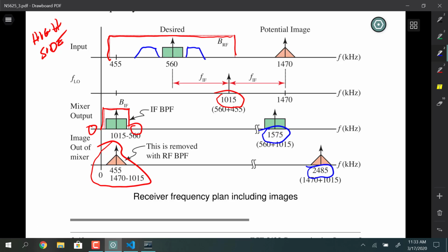So there'll be adjacent signals in the AM broadcast band, and those are going to convert and be alongside of the mixer output. But as long as you can reject them with your IF filter, they won't impinge upon any of the receiver electronics. And when I say impinge, they're obviously not going to be directly demodulated, but they could overload the signal processing chain and cause issues.